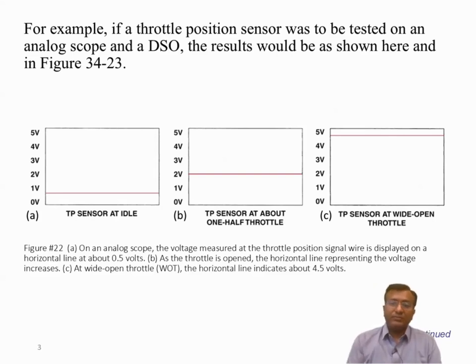The digital oscilloscope depends upon the sampling rate, which is how frequently the device captures the data points. A higher sampling rate is ideal to avoid missing short events or glitches. For example, if we are testing a fast switching ignition coil, a high sampling rate ensures that you see each spark event captured during the smallest changes.